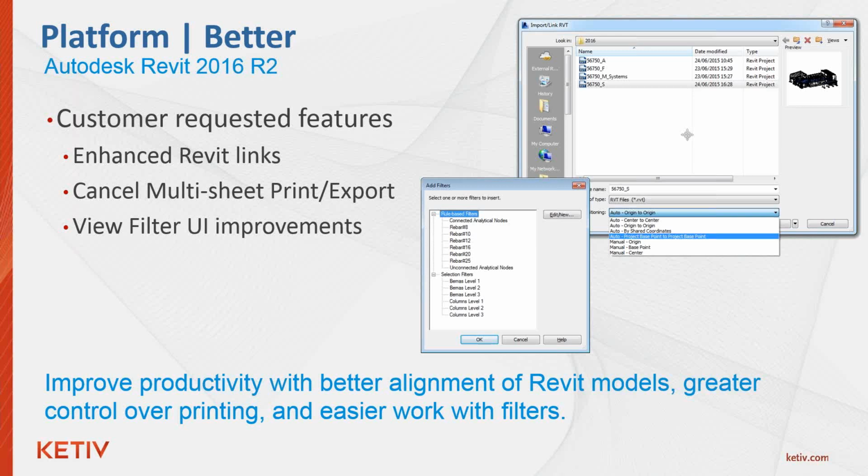And what this does is it improves productivity and better aligns your Revit models. This is another cool one right here. We have cancel multi-sheet print export. So in Revit 2016 R2, users can now easily cancel print or the export of multiple views and sheets with just one click of a button to cancel the print jobs or export operations of all the selected views and sheets. And to be honest, I really can't believe it took so long to get this simple cancel button added to Revit. I think it's finally about time. And what this does, it improves productivity and obviously saves paper if you're sending out a big plot and you realize you made a mistake. So now you can actually just click the cancel button and you're done.